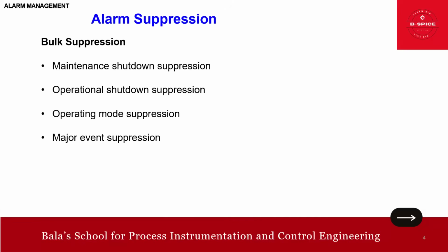For example, if a total plant shutdown is initiated, there will be a lot of intertripping of plant items, and many parameters will go outside the normal operating ranges, which is very normal, right? So suppressing these expected alarms offers significant benefit, especially if it allows an expected action that did not occur to be identified.